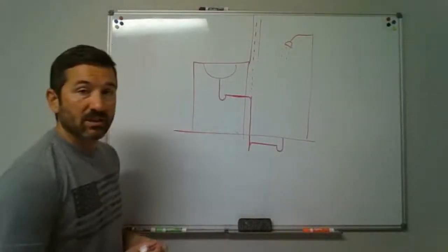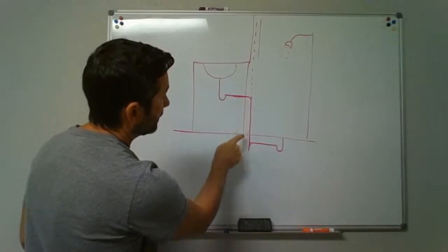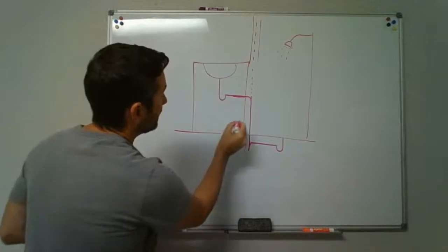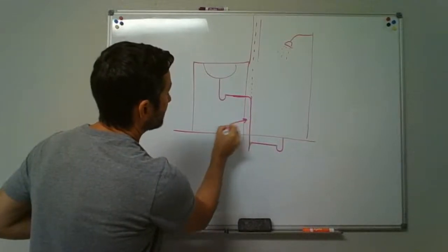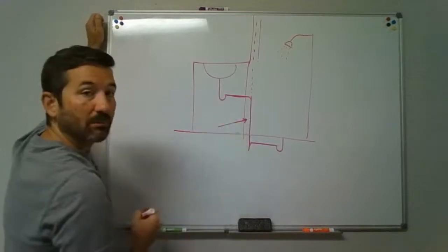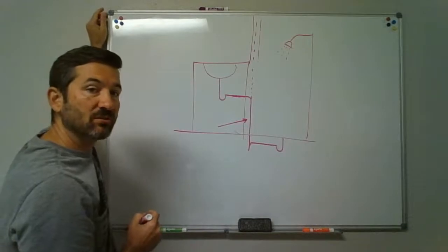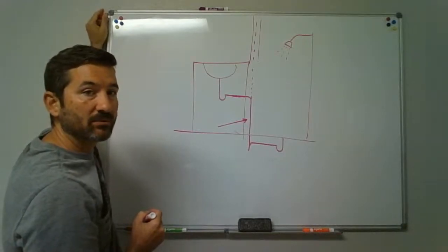And the piece of pipe that it is addressing is this common vent part that's in here. And it says how many, so we're trying to size this part of the vent. So it says, well, how many DFUs is coming from the upper fixture? Now, we've already covered this information in Chapter 7. So if you don't remember, you'd have to go back to your Chapter 7.